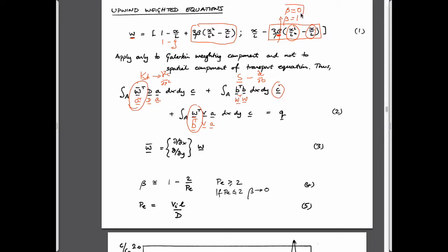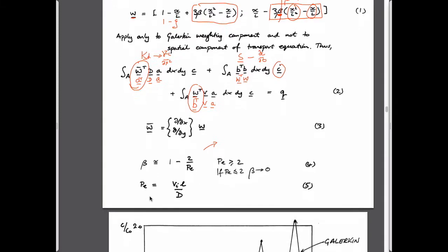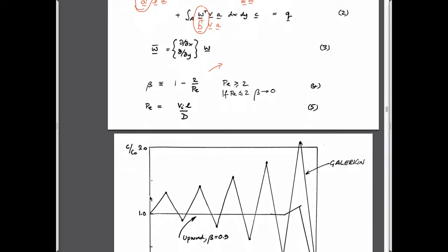So I guess you should be aware of that. And I think the actual expression for this, you can show that this is a hyperbolic cosine expression, but it asymptotes to this general behavior, and it allows you to calculate what the magnitude of this weighting of the shape function should be as a function of the velocity, where the Peclet number is the local Peclet number.